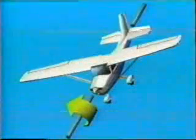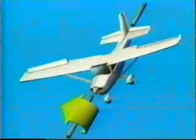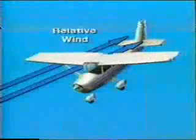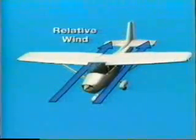Aileron deflection in the direction of the spin may alter the spin characteristics by increasing the rotation rate and changing the pitch attitude. It's also important to apply rudder opposite the direction of rotation. This allows the relative wind to strike the vertical tail surface, thereby reducing the yaw. Once rotation slows, brisk forward movement of the control wheel should break the stall.